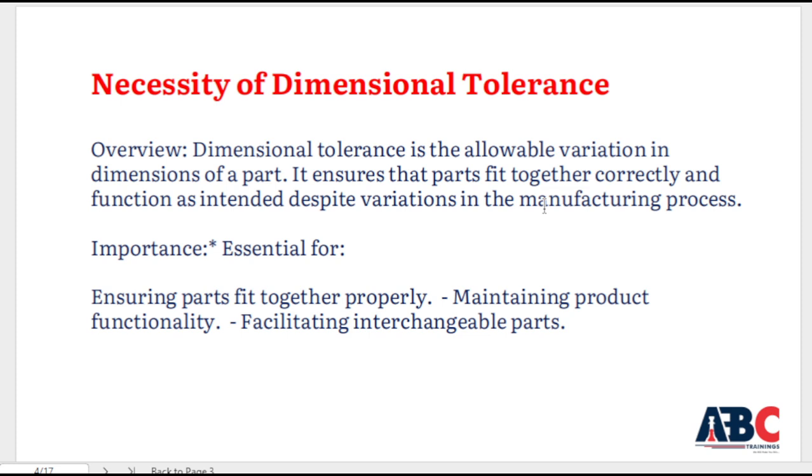Usually the dimensional tolerance is decided at the design stage, and a machinist must take care to apply the required dimensional tolerance and ensure that discrepancies are not introduced as a result of poor workmanship or measuring techniques. The tolerance is a compromise between accuracy required for proper functioning and the ability to economically produce this accuracy.